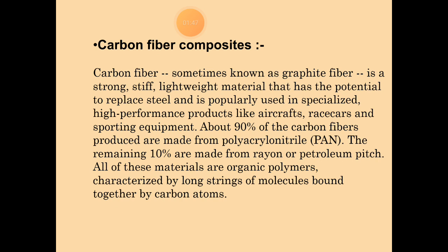About 90% of carbon fibers produced are made from polyacrylonitrile, which is PAN. The remaining 10% are made from rayon or petroleum pitch. All these materials are organic polymers, characterized by long strings of molecules bound together by carbon atoms.